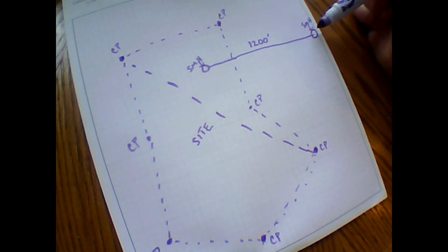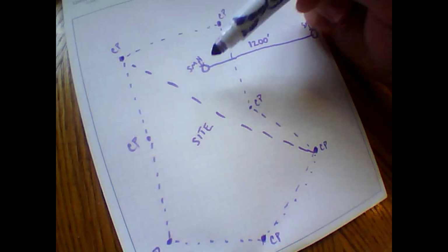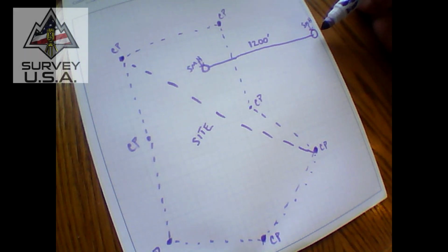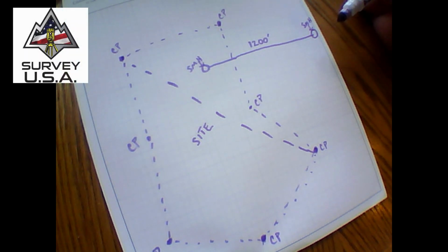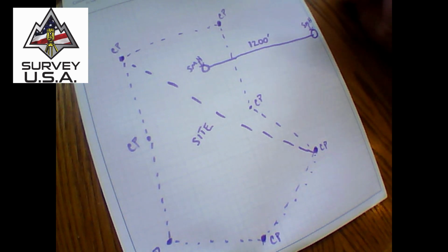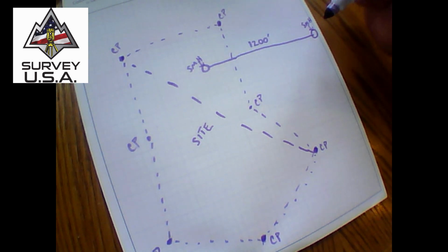Let's say this manhole is existing. You're tying in the site to the existing. Somebody surveyed that along the way. They had to have it surveyed to design it. Take a check shot. Confirm that coordinate value is what they say it is, and that you don't have error in it. At least a significant error that concerns you. Anything over half a foot or more, big problem.